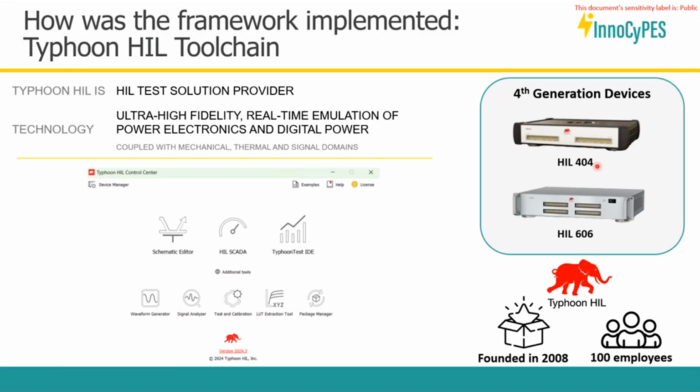So this is the Typhoon HIL Control Center. And here you can see all the tools that we have there. For example, we have the schematic editor, the HIL SCADA, and the Typhoon Test IDE. The schematic editor is where you create your model. The HIL SCADA, after the model is already created, you can use to monitor the variables, perform some actions, and influence the simulation.